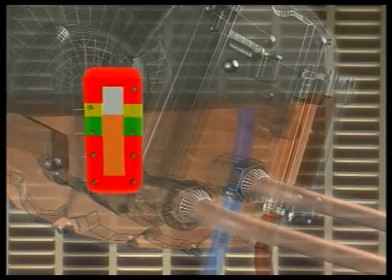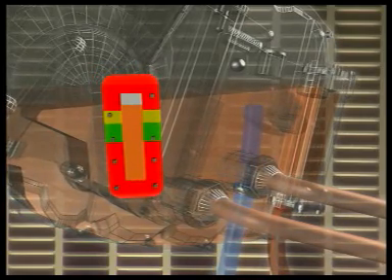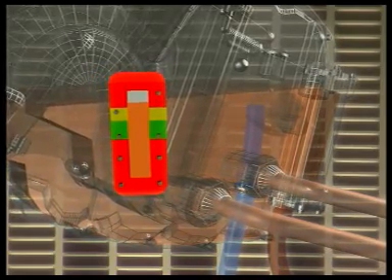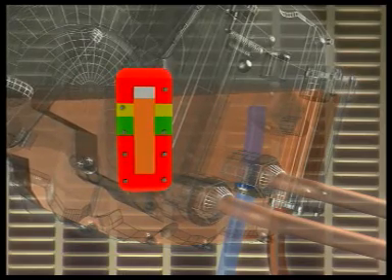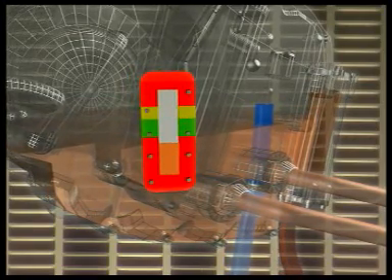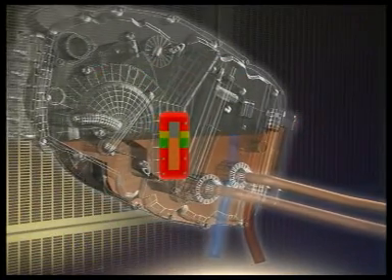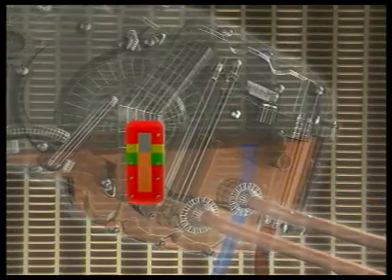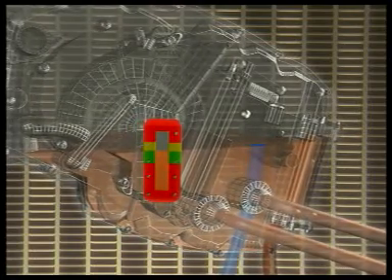If there is too much oil in the IDG, the operating temperature increases, and there is a risk of IDG disconnection in flight. A low quantity of oil may be at the origin of a low oil pressure and electrical frequency fluctuations. The generator may be lost in flight. After correct servicing, the optimum oil level is at or near the top of the green band.